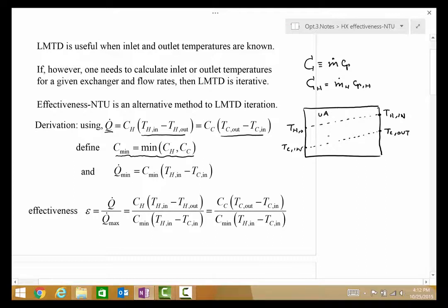As we increase the heat transfer coefficient, what you would imagine is that there's more transfer that potentially happens. So increasing UA changes both the hot stream profile and the cold stream profile. And in some sense, what we want to understand is that for the maximum possible UA, the best that we can do is to take one of these temperature distributions and have it such that at its outlet it equals the inlet temperature of the other stream.